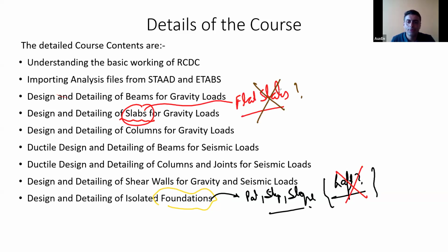So again, the answer is no. You will not be able to use RCDC for flat slabs because RCDC, I'll tell you these things later, but RCDC does not use the finite element based analysis method, or I would say finite element based analysis outputs for slab design. It will be using the coefficient approach for the design of slabs.